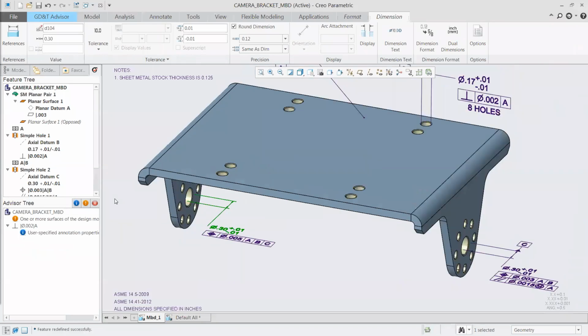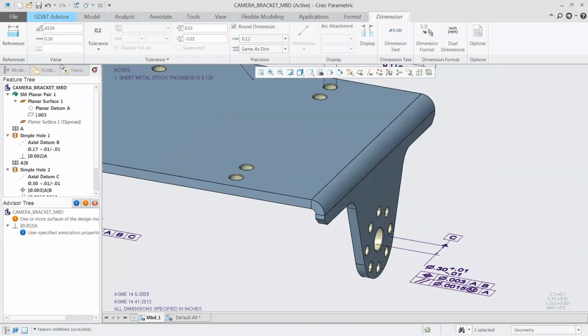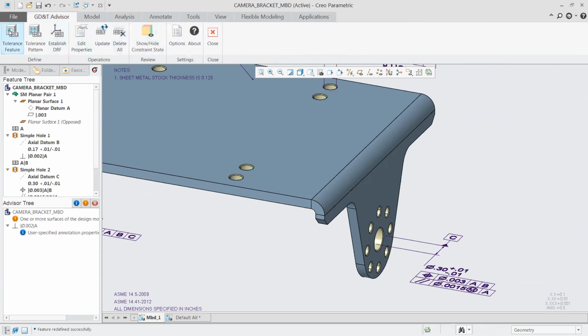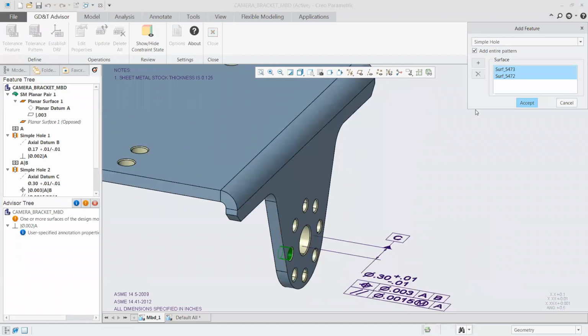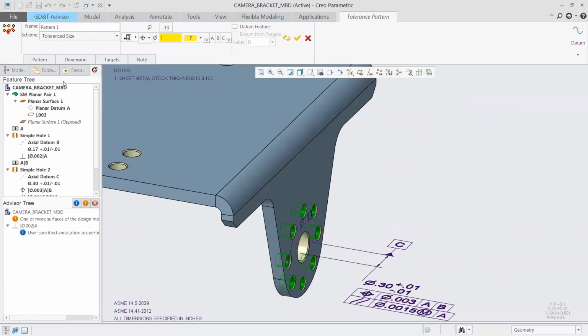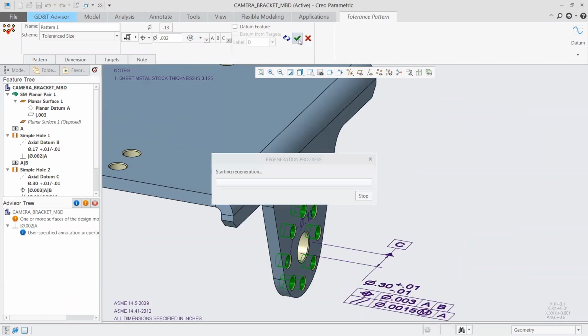All right, and now similar to before, I also want to show what it looks like to have one of these surfaces actually recognized in multiple different areas. So in this case, it's actually a pattern. We can obviously recognize that it's a pattern, but the system can also recognize that it's a pattern as well, right? We're able to apply whatever tolerance necessary, and we're able to take that and have it applied to multiple different instances of that hole. So a little bit different from what we had earlier here. Now we can actually have this positional tolerance applied to all 8 of those surfaces.